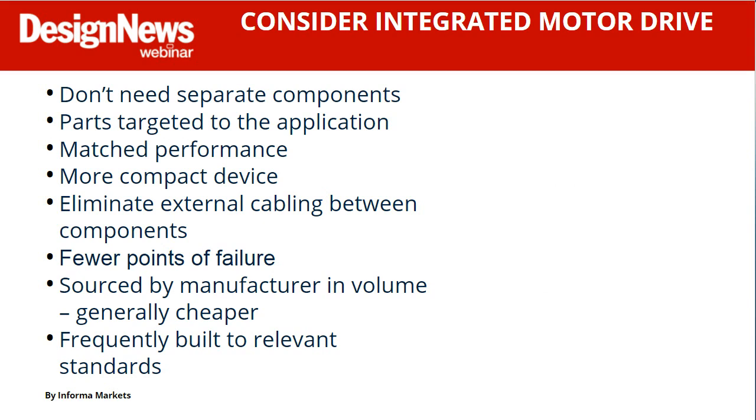The bad old days were you've got to have a motor, the drive gets wired into the motor, and the drive gets wired to the power supply. You can get integrated motor drives out there so you don't have to get the separate components. And the parts are targeted to the application, they're matched performance-wise. You wind up with something that's more compact. You cut out cabling, you get rid of points of failure.